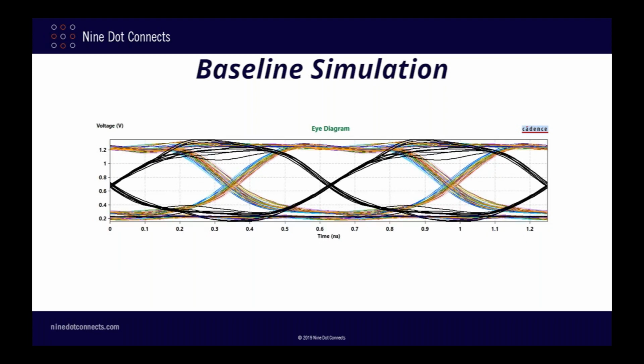I've now added in the data strobe signal, shown here in black. As I mentioned before, it is both the rising and falling edge of this signal that clocks data into the DDR device. As you see, the clock strobe transitions fall nicely within the middle of the eye opening, with lots of room on both sides and nice clean voltage levels on the top and bottom. In engineering terms, this is known as a good thing.